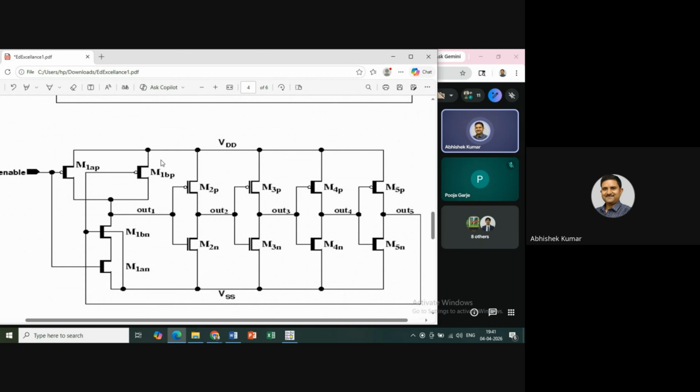So this is my complete transistor level circuit. Here, in the first NAND gate, I have taken two NMOS in series and two PMOS in parallel. Now, four CMOS inverters, which are made by the PMOS and NMOS, and one feedback path. The diagram is the same. Now here, you will be surprised to see that when enable equals 1, it will generate a frequency. But when enable equals 0, it will not be able to generate frequency. So that is our experimentation, which I want to do here.